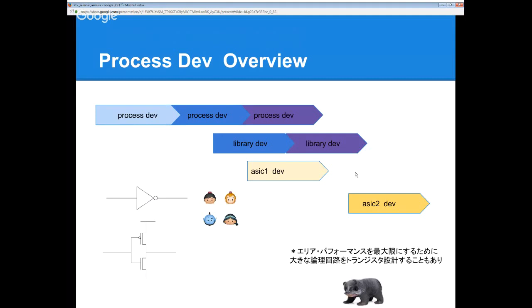So there are two types of design. The easy one is to use RTL, compile it and get the netlist. The other one is to use SPICE and the transistor model to describe the logic. So when we do a SPICE level design, we can get a more powerful logic.